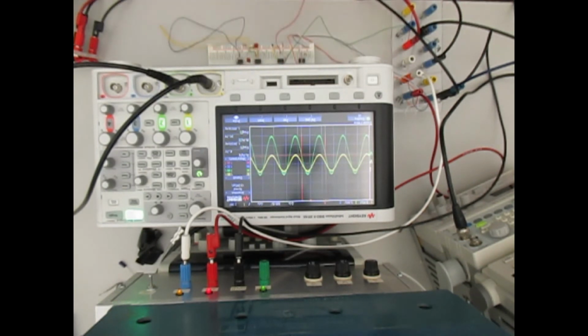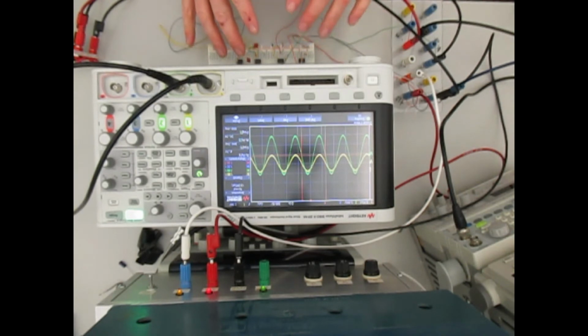Okay, so now we see, again, okay, so the output has gone up a little bit. It's 6.7 volts. And again, that's one of those, the loading effect, the voltage regulation we did in the last lab. Because the impedance of this circuit has changed, that means the source is not getting loaded down as much.